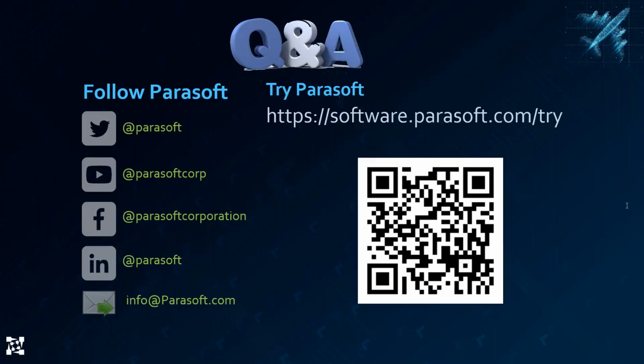Also, we had one around: are there specific coding standards that I should be using for aircraft? So MISRA, of course, depends on the language that you're using. MISRA C is extremely popular in embedded devices and in avionics, so MISRA is what I would recommend. MISRA C 2012 is, of course, the latest, Amendment 2. You may also think about what your security requirements are. We support CERT. And for C++, I would recommend AUTOSAR C++14. You may also be aware that there is a collaboration between MISRA and AUTOSAR where they're going to be combining and releasing the next support for C and C++ through their union or merger. That's going to be really nice for people.